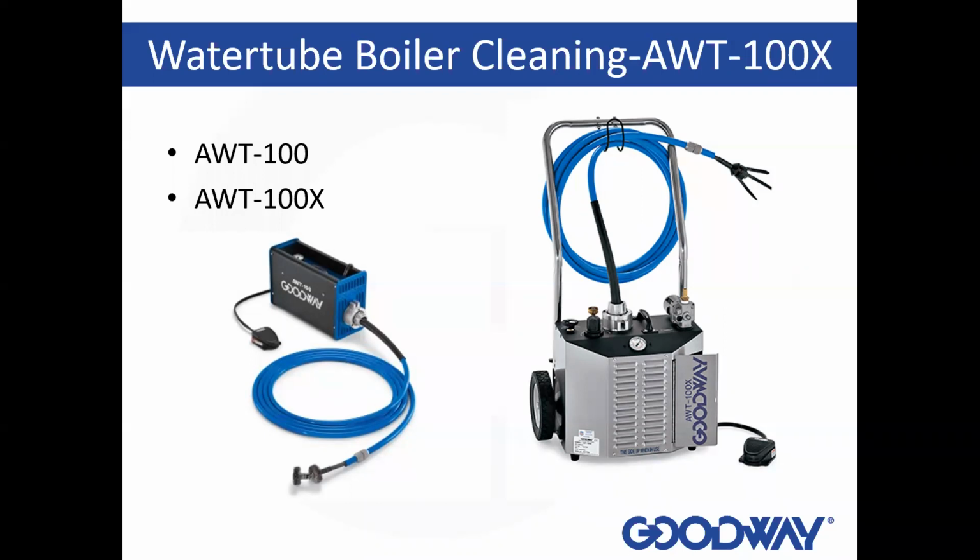And I've had guys that are newer to boilers say, well, why don't you just hose down the boiler to get the soot out? And that's just not an ideal way to do it. First, mixing water and the ash from the boiler is creating sulfuric acid, which is not good, and can damage the tubes over time. And in some states, they have regulations against using water in those tubes. But the general rule of thumb is you just don't want to inject water into a fire tube boiler.